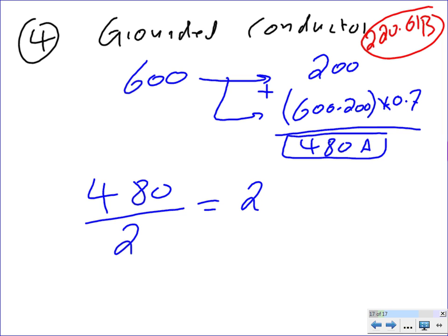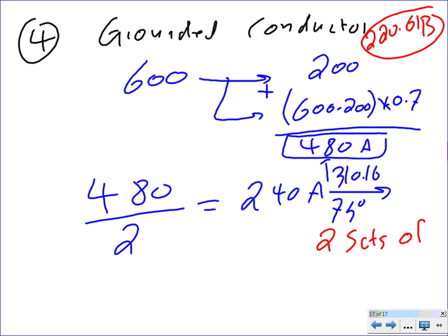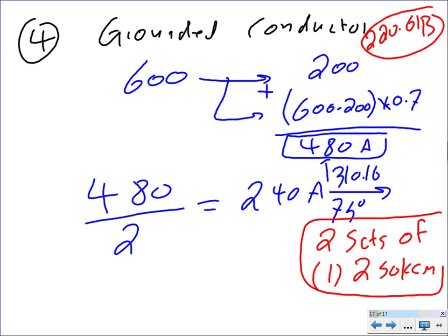I got you. 240, right? Then my friend, check me here. 310.16 table under 75-degree column. What would you guys get? 250. I have then 2 sets of 1 conductor, 250 kcmil. Spencer, my friend, you have just got yourself 2 neutral conductors. The grounded conductors are the neutral.